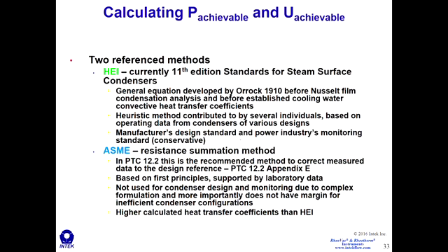Now there are 2 different methods to monitor performance. The HEI method is almost used exclusively, and this is the one that I would recommend to use for monitoring performance of the condenser. HEI recently released its 11th edition, I think in 2012. There have been very slight changes made over the years. I'll show you one of the most important ones in recent past in a couple of slides. But just a little background on this method.